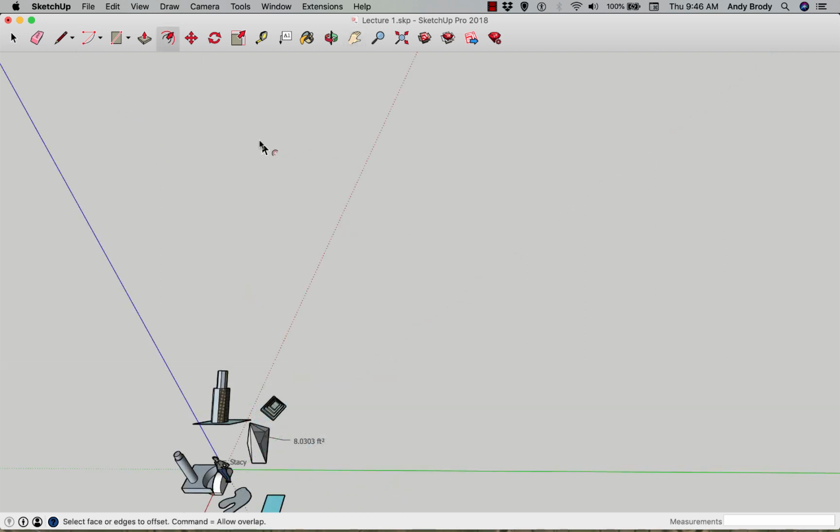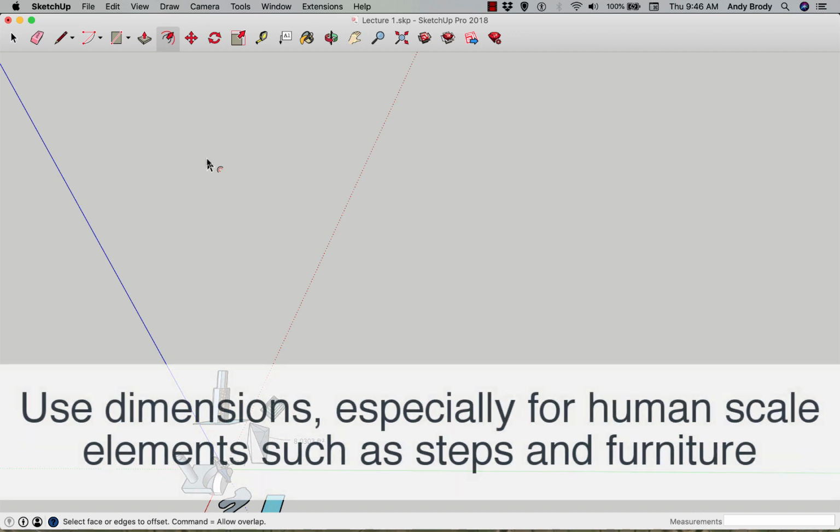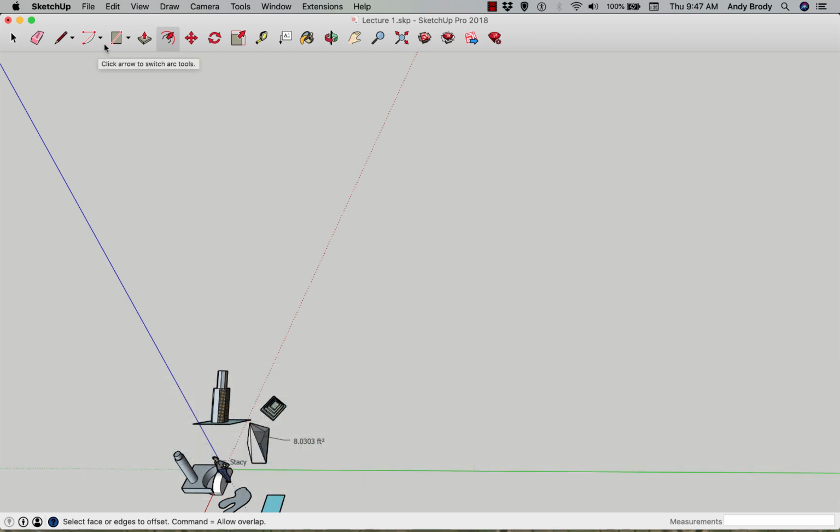So when you draw something architectural, you definitely want to be as accurate as possible. And I happen to know the size of the base that we need for our little temple, and it's 80 feet by 44. So we need a rectangle. Click on the rectangle tool. You could also type in R, I believe, for rectangle. I'll click once to start the tool.